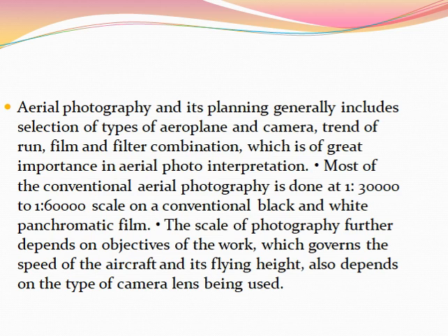Then, for extensive ground coverage, satellite imagery is most useful. For more specific and detailed information such as geotechnical studies, mineral exploration, groundwater surveys, land use planning, and town planning, large-scale photographs are used, such as 1 is to 50,000 to 1 is to 10,000, which are widely used and most suitable.